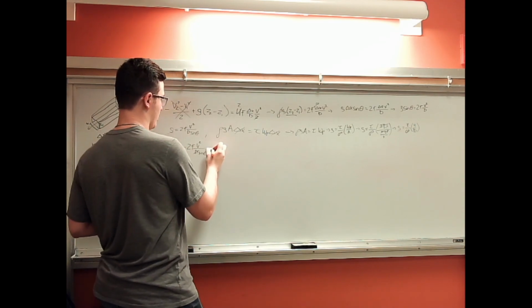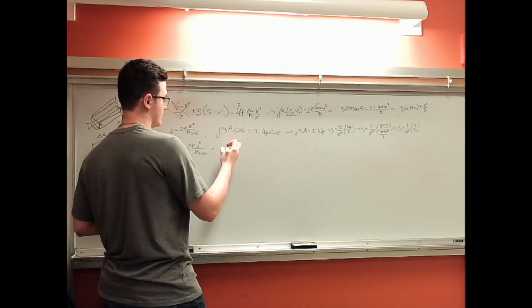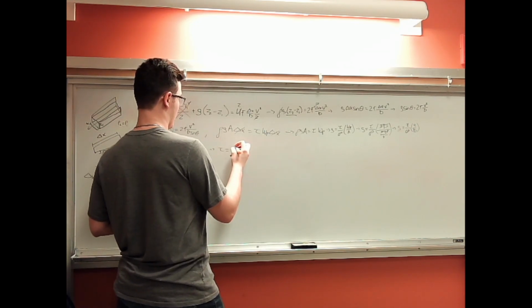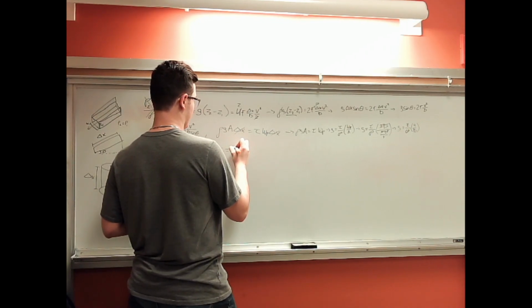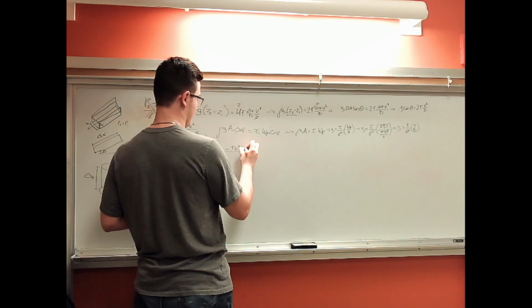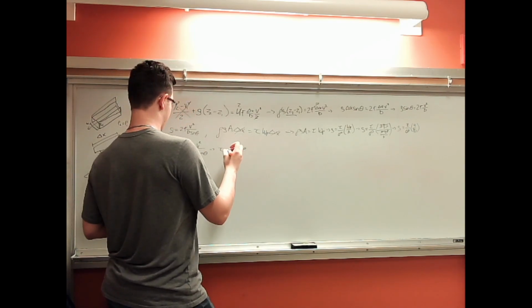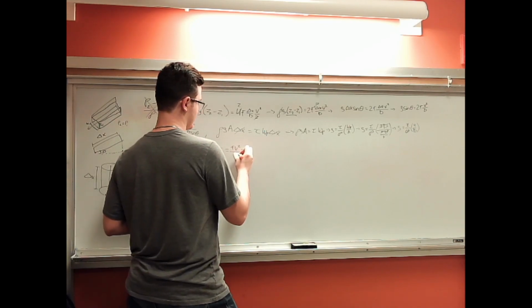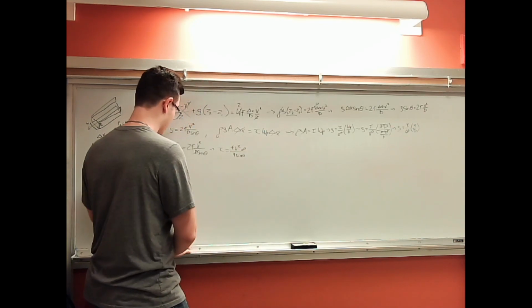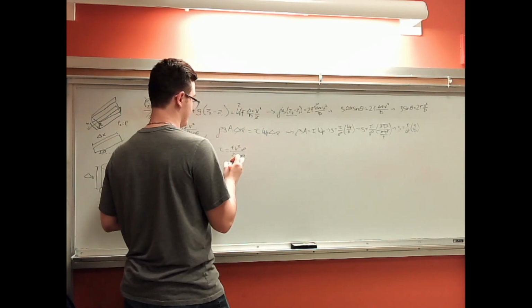These diameters cancel, and if we want to get this alone, we multiply across, goes to tau, the shear stress is equal to the Fanning friction factor times the velocity squared times the density of the fluid, divided by 4 sine theta. This 4 cancels with this 2, so it's just 2 sine theta.